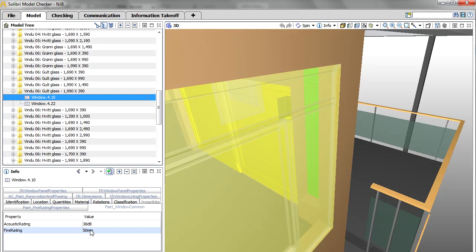To summarize, the detailed BIM data extracted from an ArchiCAD project can be mapped to their corresponding IFC standard or custom data. You can achieve this in any format required by the documentation standard or preferred by the consultant. A mapping rule can be a simple one-to-one correspondence or a combination of several model parameters. In any project, you can maintain a list of several mapping rules. You can save them to an XML file, which means they are easily transferable among different projects and coworkers. As you can see, for any format you may require, the BIM data from ArchiCAD models are ready to roll on the OpenBIM superhighway.